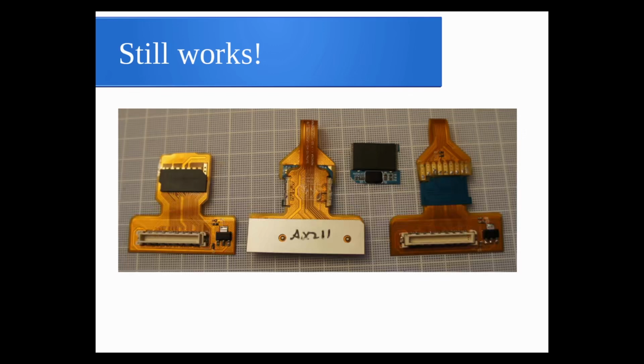Now, there's something interesting. Bunny showed this picture earlier, which shows the AX211, nicely labeled, right in the middle, with no NAND attached anymore. The idea was you're supposed to use the ROM emulator that we wrote to emulate the ROM. But the interesting thing is, with this particular card, if you reset it, set it to command 0, it'll still respond to some commands. It'll respond to command 0, because that means go ready. It will respond to things like turn CRC on or off. But the go ready command, the hey, I want to actually read the file system command, doesn't work, because of course it doesn't have either firmware or any NAND flash to store it on.